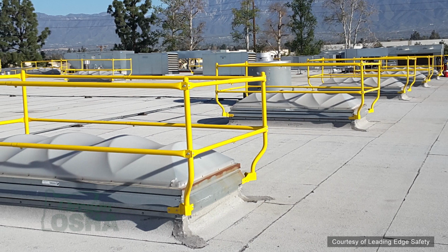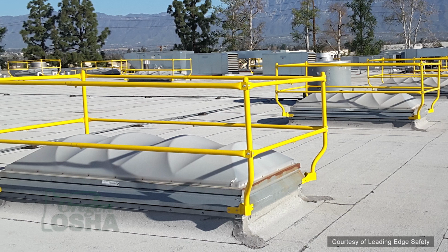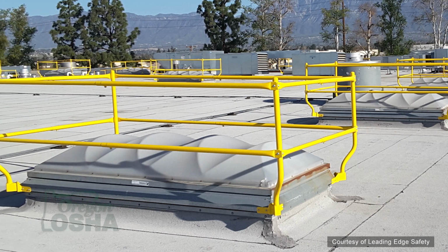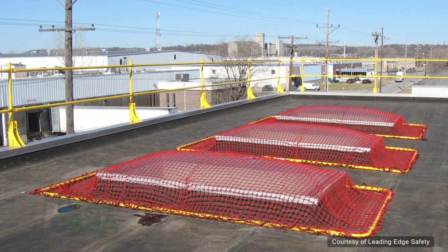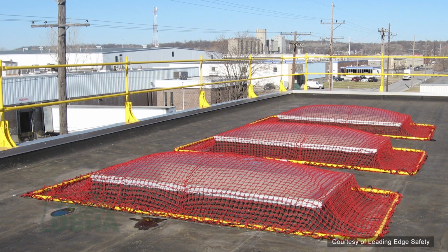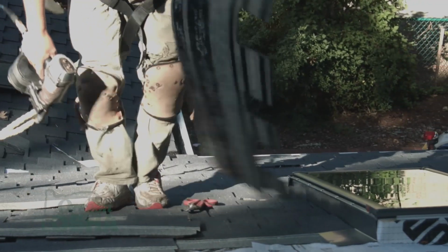If you're up on that roof, what we want you to do is prevention. We always want prevention. Skylight covers, guardrail systems, demarcation, anything you can do to protect against those skylights comes first. Temporary guardrail systems, like we said, block it off so you can't get to it. Most guys just want to tie off and run around. But remember, with skylights you could tie off on this side, walk up to a skylight, and you're fine.